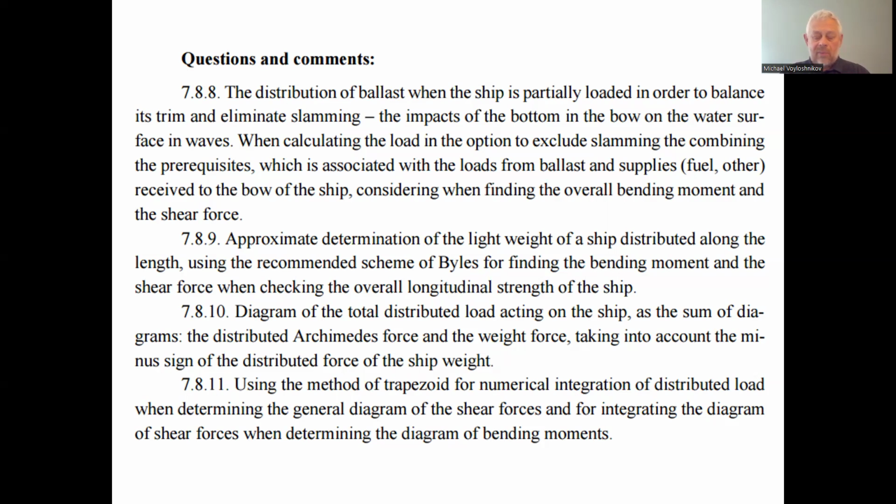Thus, we have to find the bending moment and shear force for the dangerous state of the navigation of the ship. Dangerous state could be if we have the ship partially loaded, for example, if we have two separate cargo capacities, we can consider loading only one of two cargo capacities. Which one? It could be, if you have equal ones, not the middle cargo capacity, but any one, the fore peak or the stern of the ship. We have considered one full and the other one empty in the middle of the ship.